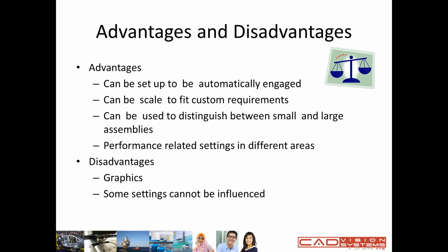It also can be used to distinguish between small and large assemblies. So it's also a performance-related setting in different areas. Now I'll come to the disadvantages. There is some impact on your graphics, and also some settings, like the automatic settings and some other settings, that you cannot influence. So that's the disadvantage of large assembly mode.